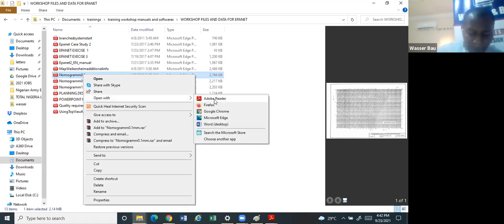With the flow, the roughness of the material, and the slope, you can size any pipe. The most important input parameter to size a pipe is your flow. Then your slope will also be important because the slope will be able to help you determine the velocity at every point. And we all know that the velocity is very important because there's a minimum value expected in the velocity in the network, and there's a maximum value.